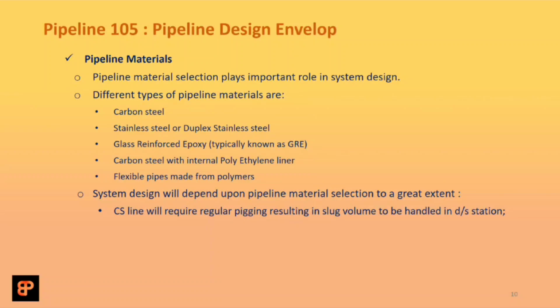That means as part of your routine maintenance and inspection, you need to keep removing that liquid out of the pipe. If you don't do that, then the liquid separation happening in the pipe will leave stagnant liquids sitting in the bottom of the pipe along the pipeline.